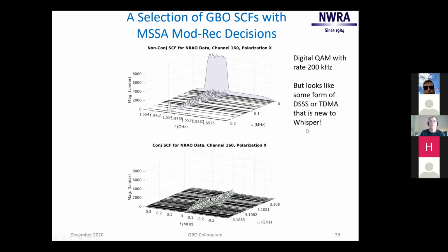And so it goes. Now this is a sort of a new kind of signal to me. I was grateful for seeing. You can see it has lots of features, just like a direct sequence spread spectrum signal, a prominent feature out here, but it doesn't look like any kind of generic DSSS signal. If it was like GPS, we'd have three big features here. If it was like QPSK, this stuff would all be essentially negligible. And if it was SQPSK, there'd be two features. So it's either a TDMA style signal or a new kind of direct sequence spread spectrum signal.